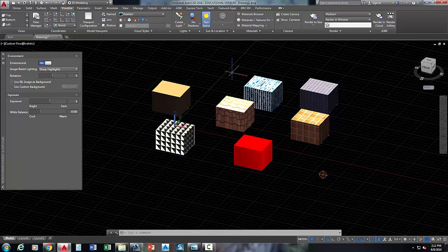And whether you're using AutoCAD or another program for it, there's a lot of programs out there that'll calculate this for you. It's nice for energy efficiency with green building nowadays. How big do I need to make my eaves? Because the winter sun is a lot lower than the summer sun. So I can test and see where that sun is. Is it casting shadows? Is it really bright in my windows? In Austin on December 26th, at 5 o'clock p.m. Is that the worst time? Do I need to make my eaves a little bit bigger? Do I need to maybe plant a tree here?